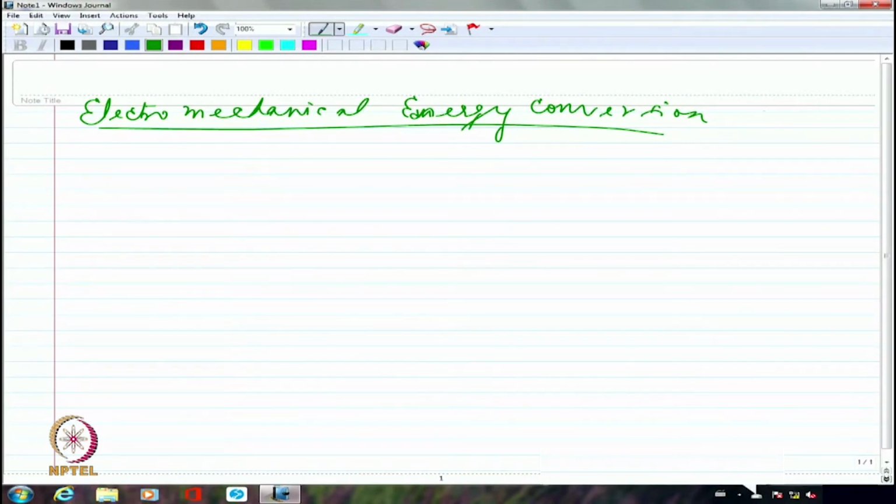So that is going to definitely ask for more amount of current. If flux has to flow through the air gap also, it will require more current. So as a rule, any moving mechanism is going to demand more amount of magnetizing current, right?